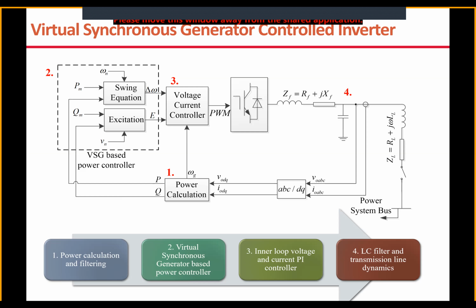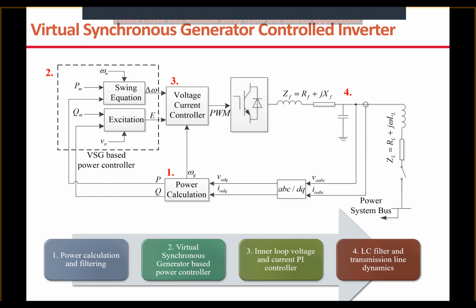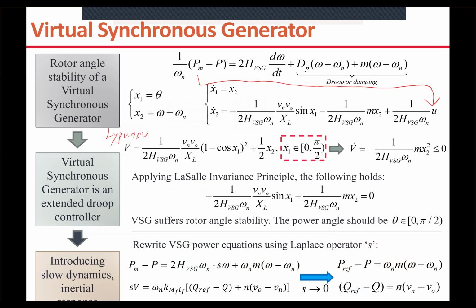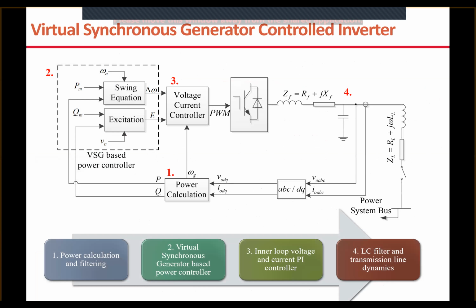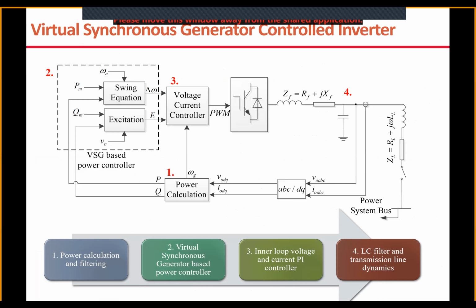So the ERCOT case seems to have a much higher nadir, like 59.7 hertz, while the UK case has a much lower nadir, like less than 49 with respect to 50. So the delta frequency is 0.3 hertz versus 1 hertz. It seems the UK system is more tolerant to frequency deviation in general. Any reasons for this? I don't know the reason.